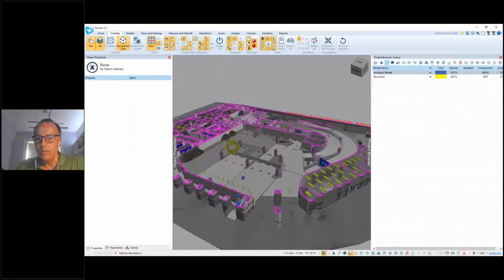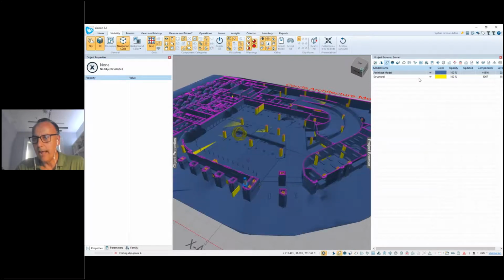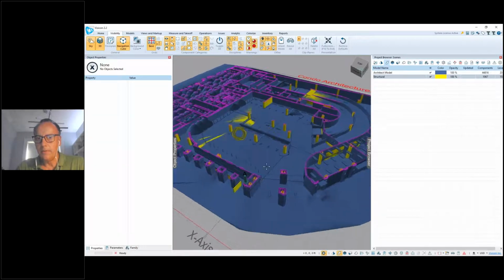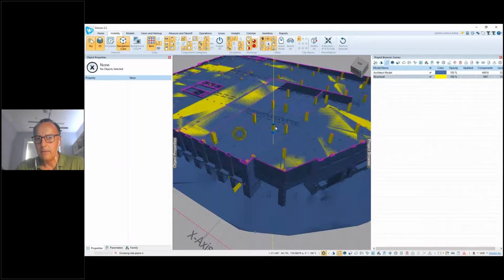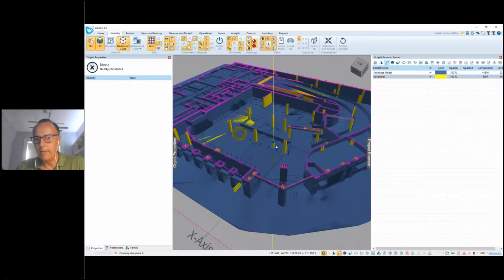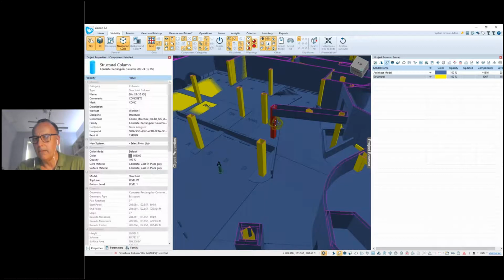And now, without having to bother the modeling team or rely solely on the CAD file or the PDF files, I'm going to go to my model color mode, right? Remember, our structural model is yellow. The architect's model is blue. And I can now, using the clip plane widget, go up and down and very easily verify. See, this is the missing column in the architect's model.